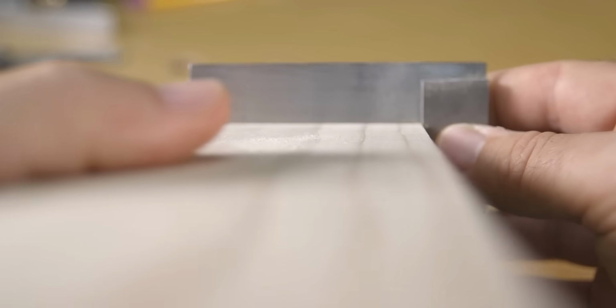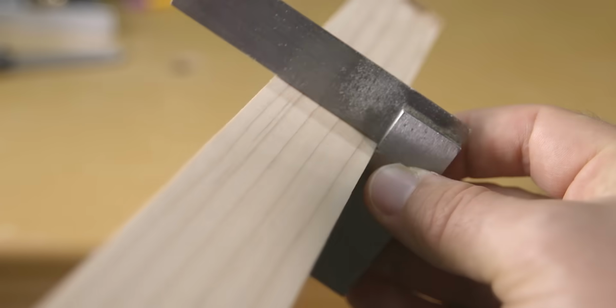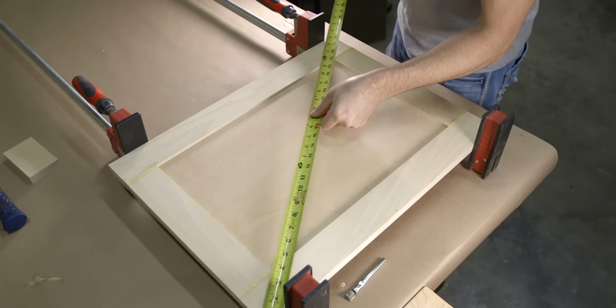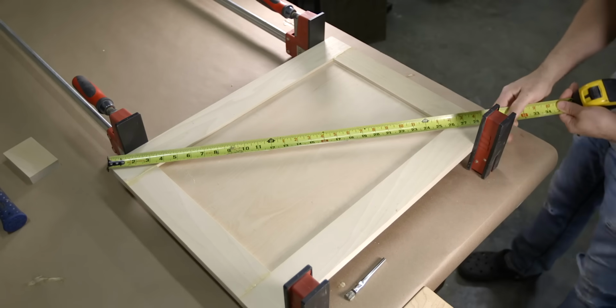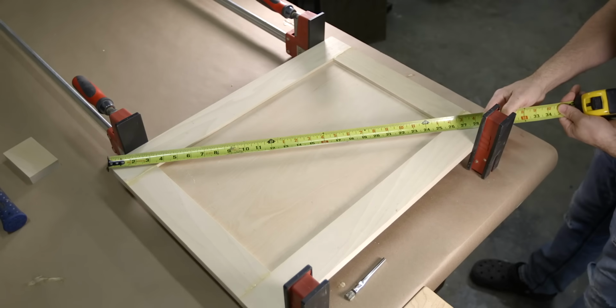In carpentry and woodworking, it refers to checking the squareness of the faces, edges, or the ends of boards. It also refers to checking if something you're building has equal diagonal measurements, which verifies that it is indeed square. The term square is also used to label a group of tools that are specifically designed to mark and check for squareness. Let's look at 4 of them.